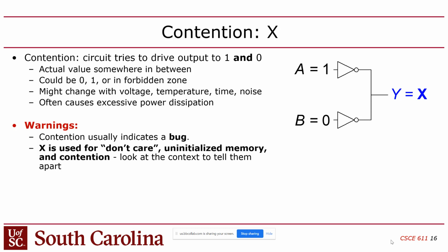However, the problem is that Verilog, unlike VHDL, only has a limited number of values. So obviously there's 0, 1, and X, as I mentioned. However, what happens if, for example, you have a register that is not initialized? In real life, it would just come up as a random value, but in Verilog, it uses that same X, which means don't know or undefined. VHDL has a U that it uses for that, so VHDL is a little nicer in that sense.